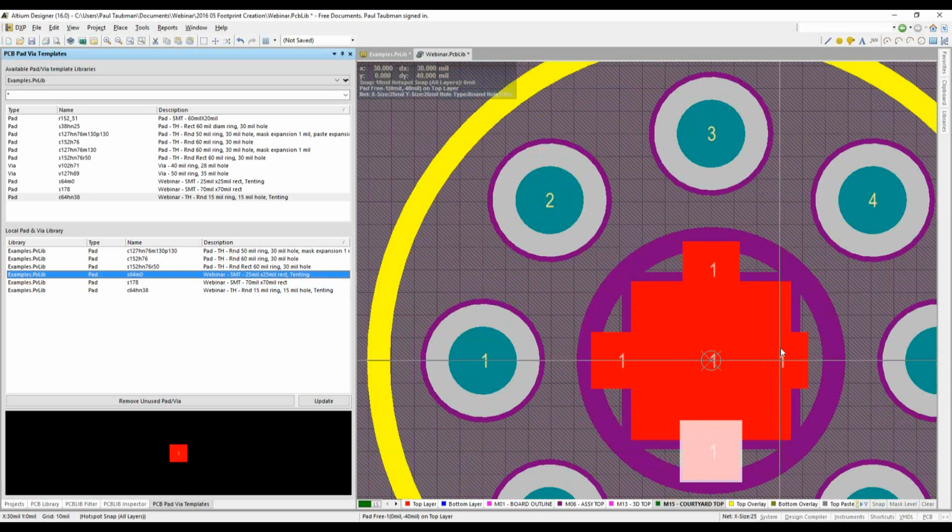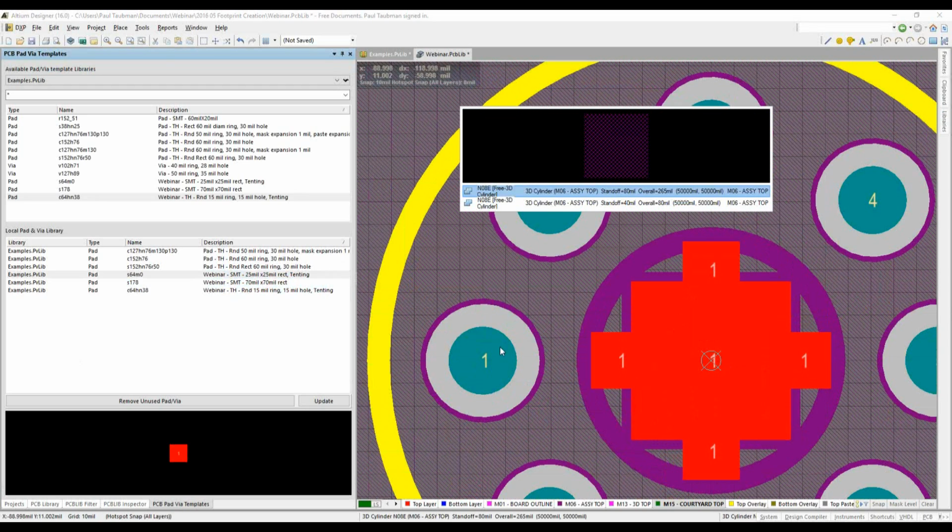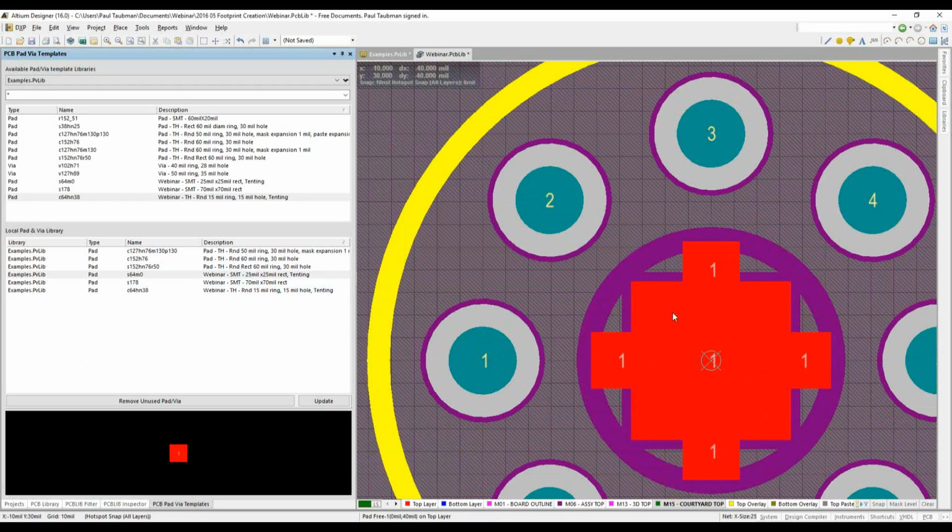Unfortunately, it's keeping these. Now, I do need to change one thing. Notice that in the middle here, all these pads do need to be changed to another value. I would recommend that they be given pin 9, and that a separate pin altogether is given for pin 9. The reason for that is that this would currently be associated with pin 1. So even though they're not attached to each other, Altium will say pin 1 is associated to this and all of these over here.